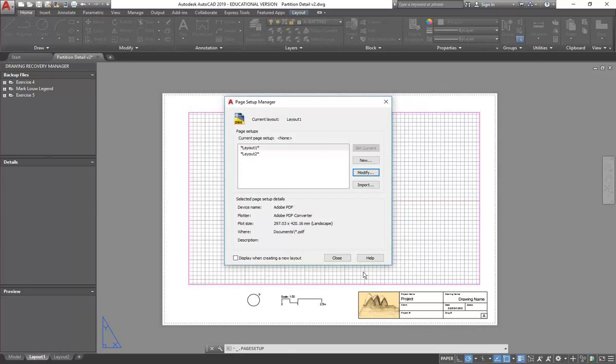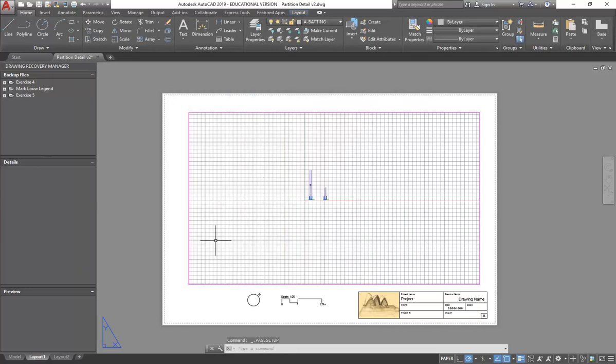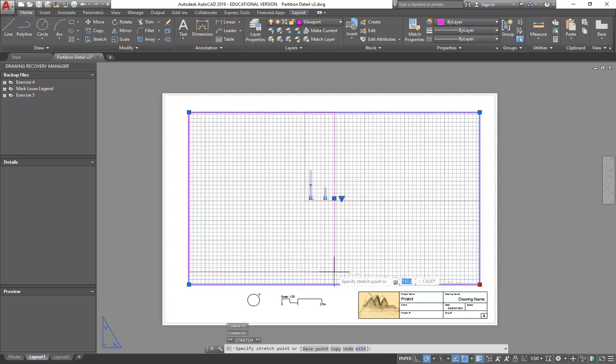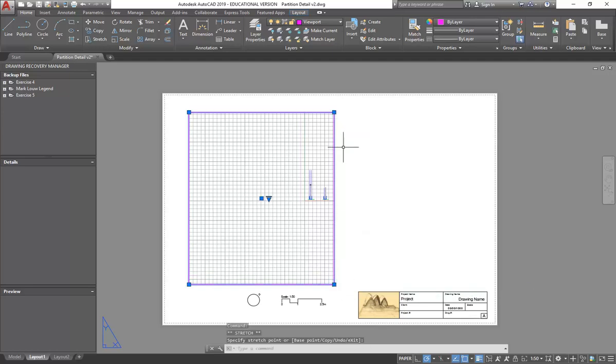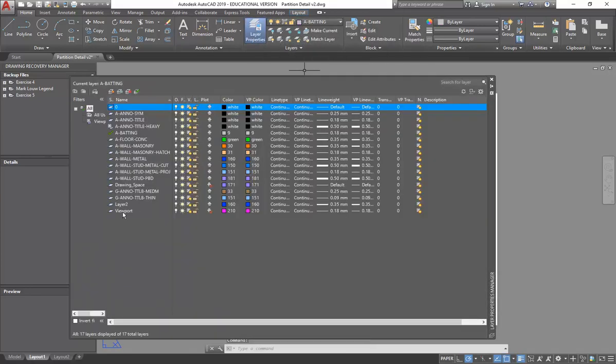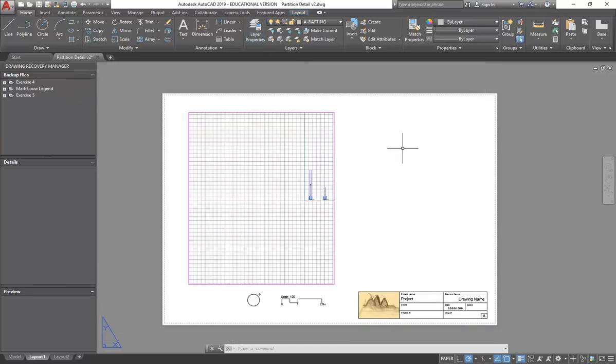So, going back to look at the viewport, do you remember how to make viewports if you need them? Well, I have to show you anyway, because we've got only one viewport there. So I've selected it, and I'm going to make it smaller, about half the size that it is now. It's on my viewport layer. If you remember in the layer properties, that layer is set to be non-printing, so I can leave the border visible.